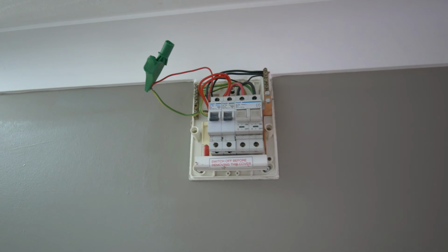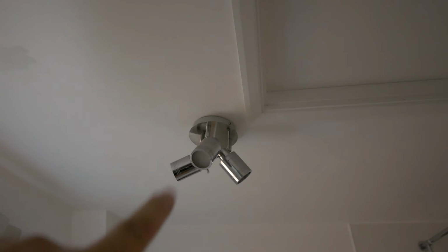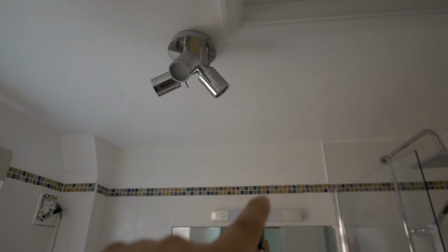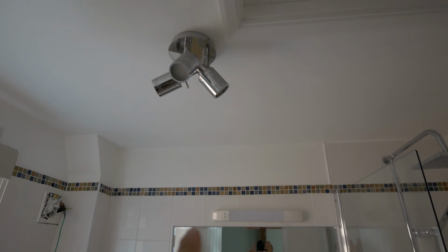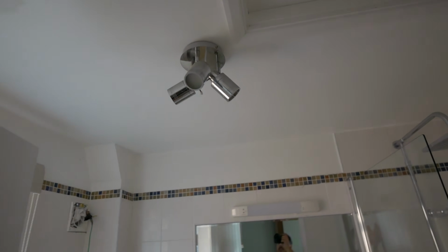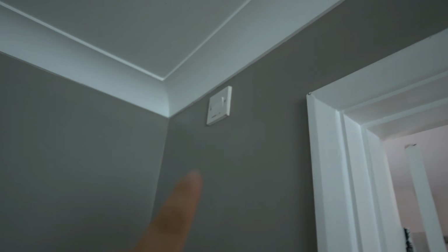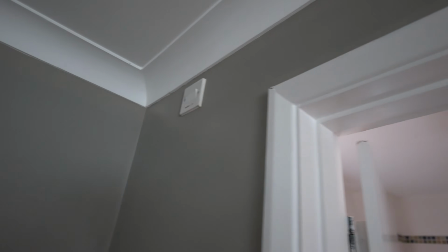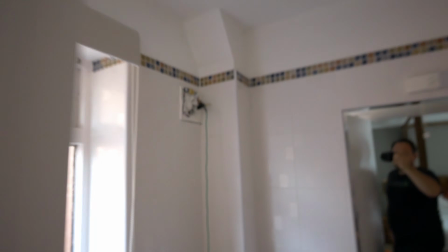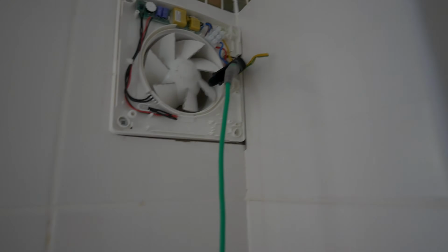So I've linked out the line and CPC for this lighting circuit. I've been and dropped a few of the accessories and had a look around, and as suspected, the end point is in this bathroom. Line and neutral comes into this light fitting here. The light above the mirror doesn't have an earth, it's just a class 2, they've just taken line and neutral to it. We then feed back to this isolator on the bathroom fan, and then it comes over to the fan itself.